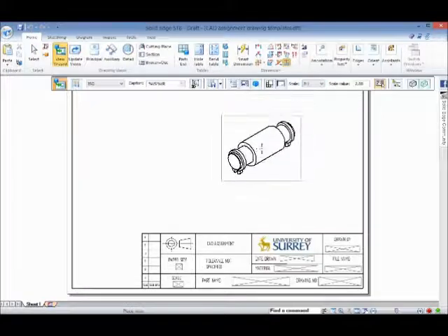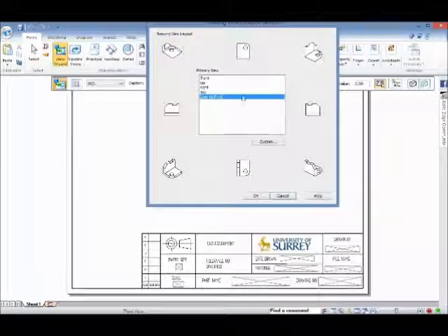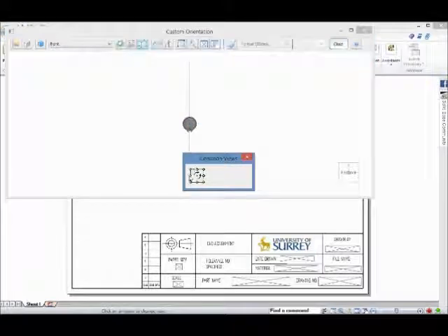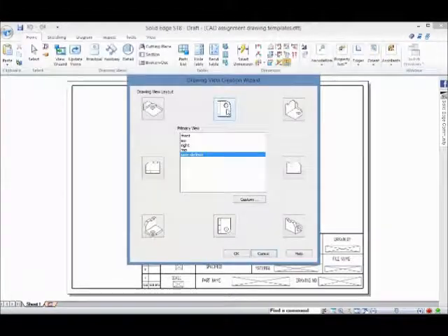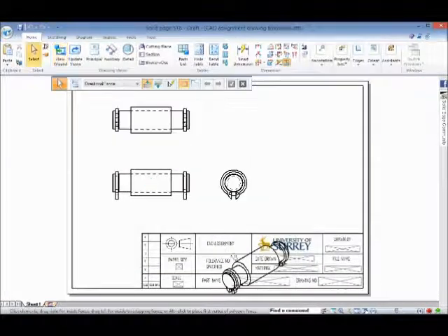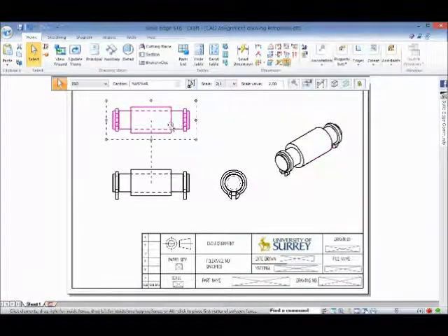size of the view is selected, then you can go on to select this icon, which allows you to choose the views. First, you need to use a command and find your front view. That's a front view. Then close this command menu, then select the top view and the isometric view from this graph, and click OK. You can see after you click OK, if a box appeared here, you can drag the isometric view there.